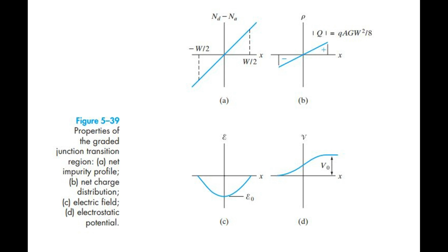Most of the conclusions we have made regarding carrier injection, recombination and generation currents, and other properties are qualitatively applicable to graded junctions, with some alterations in the functional form of the resulting equations. Therefore, we can apply most of our basic concepts of junction theory to reasonably graded junctions as long as we remember that certain modifications should be made in accurate computations.